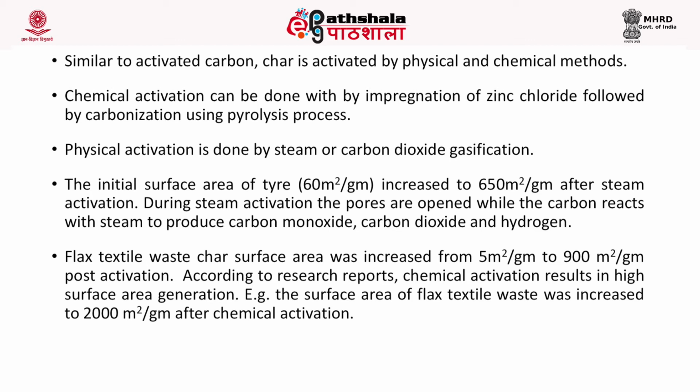This steam activation will open up the pores in the carbon once they react with the steam, and the carbon will be converted into carbon monoxide, carbon dioxide and hydrogen. Likewise, the flax textile waste char surface area can be increased from 5 meters squared per gram to 900 meters squared per gram after activation.